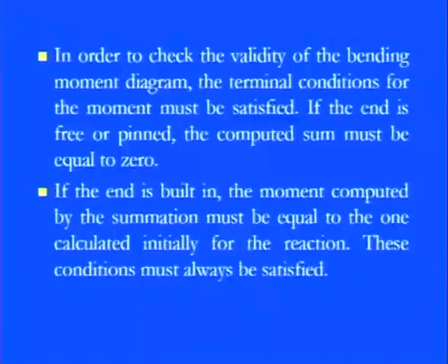If we are saying that the bending moment or shear forces are there in a beam under the application of these load conditions, we need to satisfy these conditions, and only then can we say that whatever sign convention we took to analyze the shear force as well as the bending moment is correct, and whatever values are coming are in the right direction.